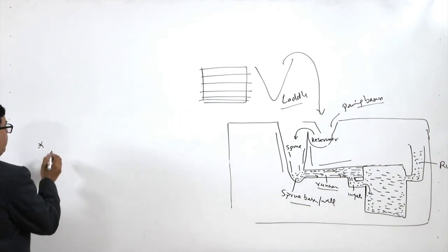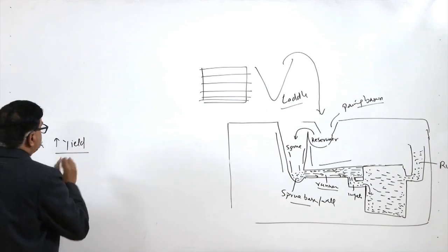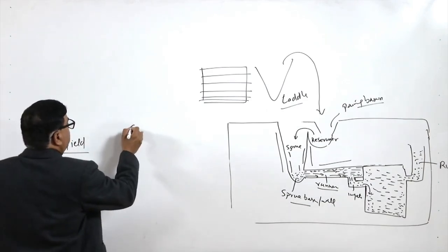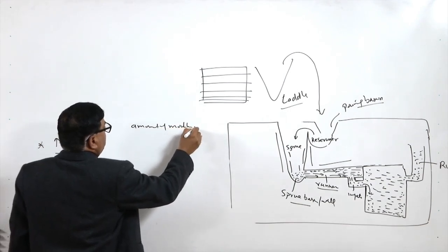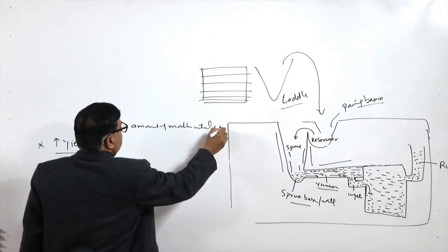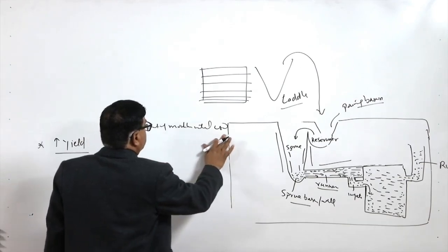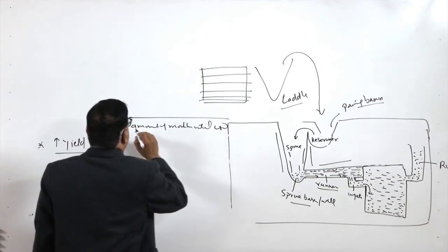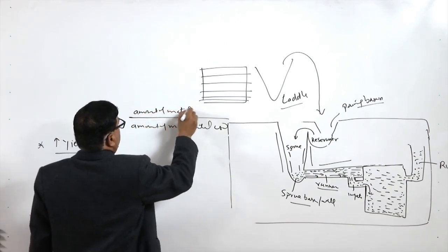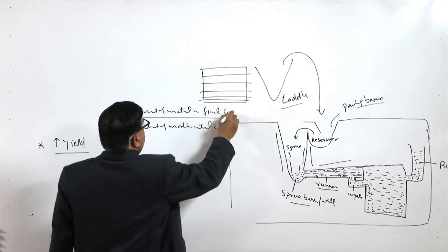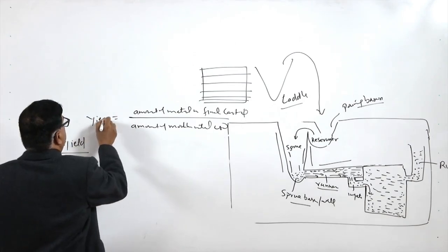Apart from feeding in the required quantity, there are two more functions. The design of the gating system should be such that it increases the yield. What is the yield? Basically, it is the ratio of the amount of the metal in the final casting to the amount of the molten metal used. So, the ratio of these two gives us the yield.